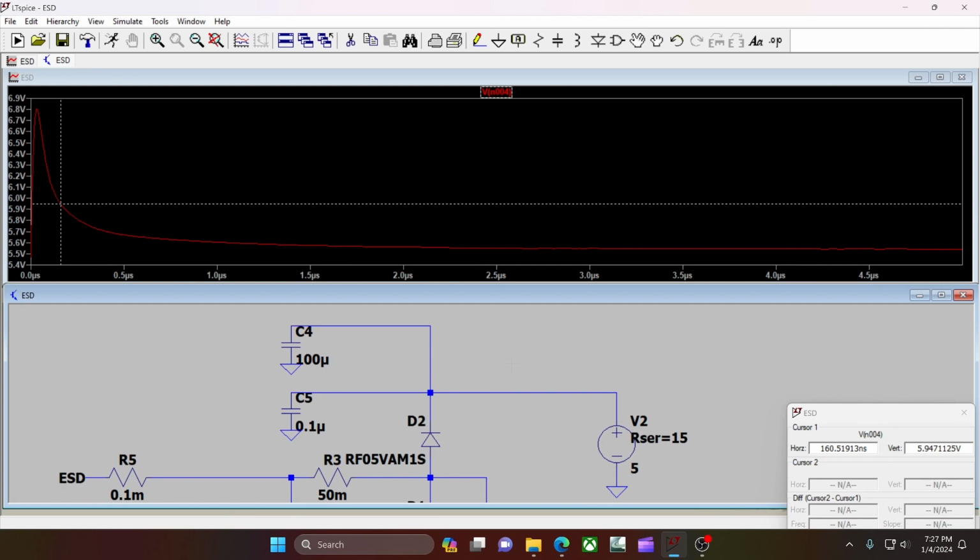Wow. I'm almost speechless. But it makes sense, right? Your VCC is 5 volts, but this voltage from your ESD is higher. So that goes into your capacitors here, which makes it so your VCC does not rise as much. So yeah, use caps. You're using good decoupling capacitor strategies anyways, right? Close to the IC, big values, right? Right? You better be.